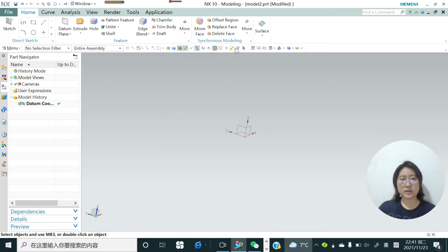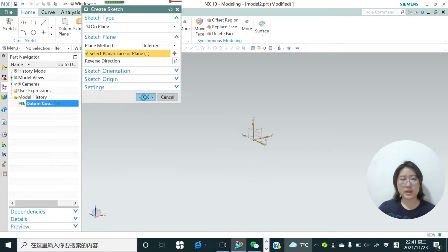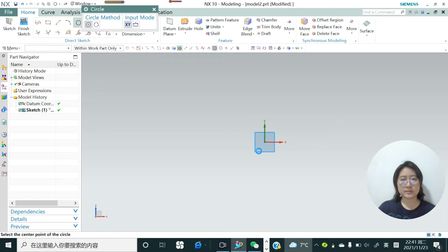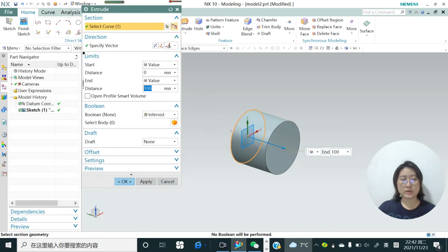And here is the capture tools. For example, if I have a sketch on a plane where I just created a round shape, the sketch doesn't necessarily need to exist as a feature; you can directly choose to extrude this round sketch. Here you can change the distance you want, let's change it to 50, and hit Apply.